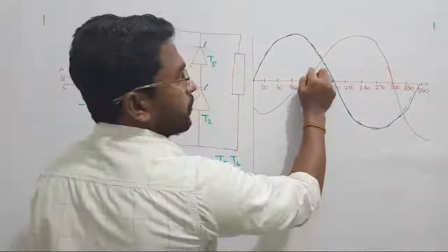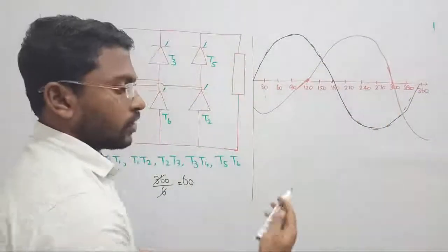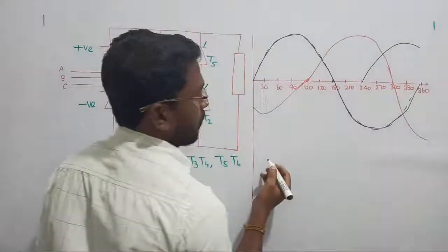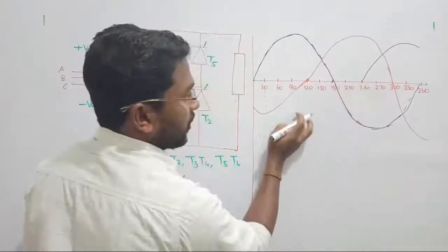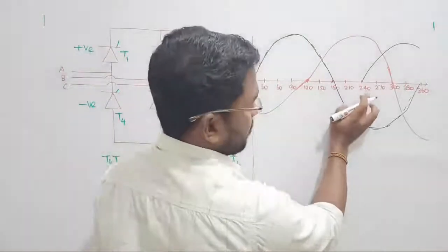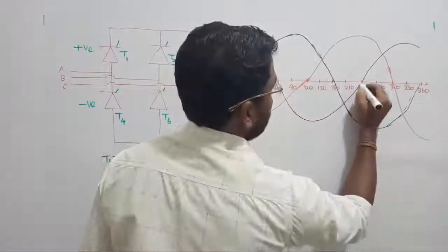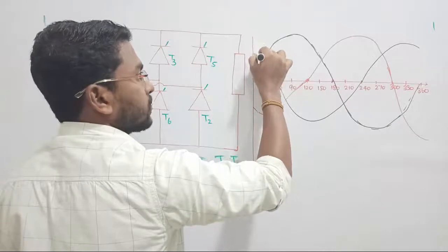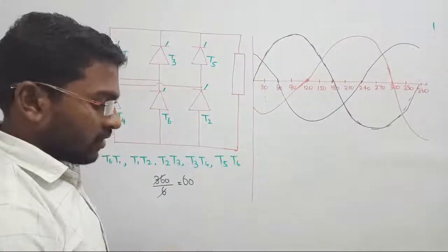after 120 phase B will enter and then from here after 120 phase C will enter. If you observe, the phase C waveform will give its presence from this point onwards. Prior to that, if I subtract 180 degree from this, again in the negative half cycle you will have 180. So if you subtract 180 from this, you are getting 60 degree. So it will become the next waveform, such that at 60 it won't touch the maximum value somewhere here. That's all. So totally we have drawn three waveforms here.